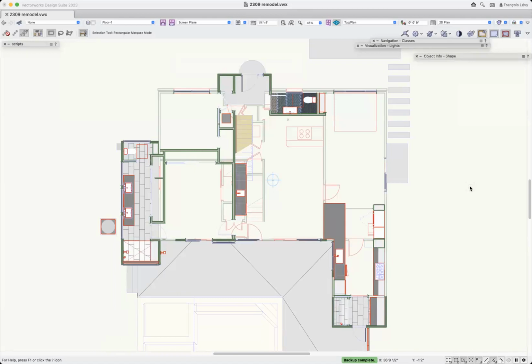Get it? Okay. And so what you could do if you needed to show as-built conditions is just have a design layer, create a viewport with an external reference to your as-built file, and show the floor plan on your sheet layer. So you could have on your demolition sheet, for example, existing and demo. Right.